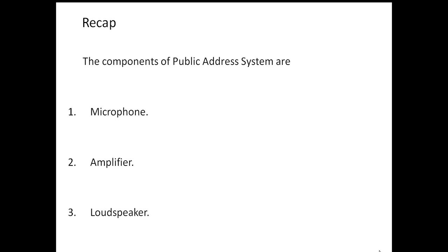The person who is speaking from the stage is connected to an amplifier, through wire or wireless. Maybe around every 100 meters, we have to place one more amplifier, which consists of an amplifier circuit. That amplifier will increase the amplitude of the speaker's voice or signal to various places, however long the gathering may be. From there, in all directions, we have to place the loudspeakers.